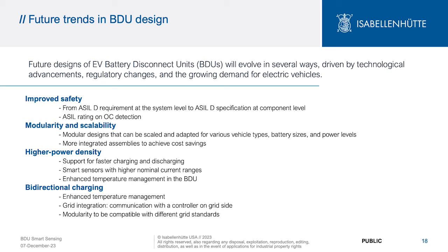And if you think about it, that makes sense because the overcurrent detection is very critical in the vehicle, because if an overcurrent detection is not reliable, in case of an accident, this can have a high impact. The overcurrent detection will typically trigger a fuse, a mechanical fuse, or in most cases a pyro fuse, and that will disconnect the battery in case of an isolation fault or an accident. So if this system doesn't work properly, it directly impacts human safety.